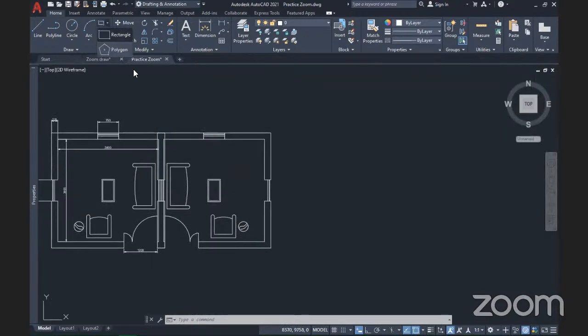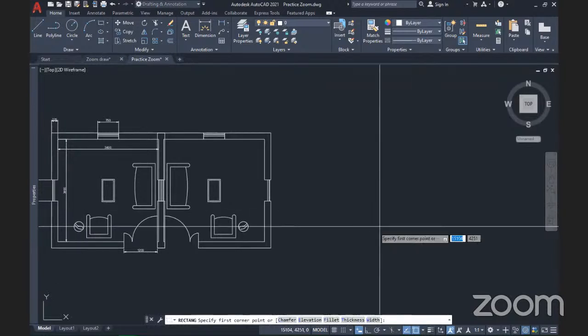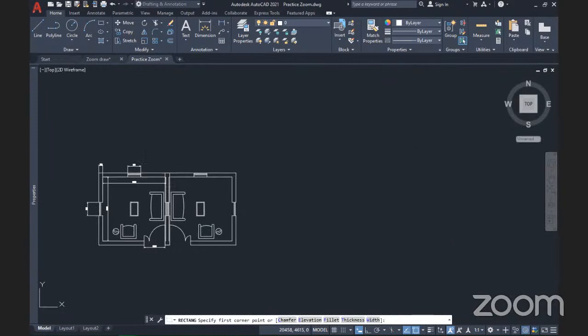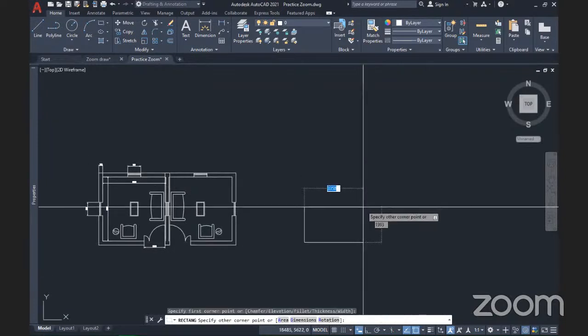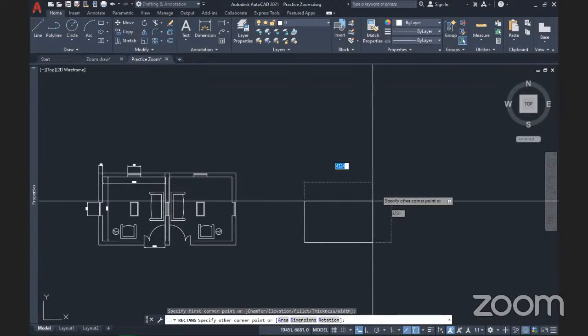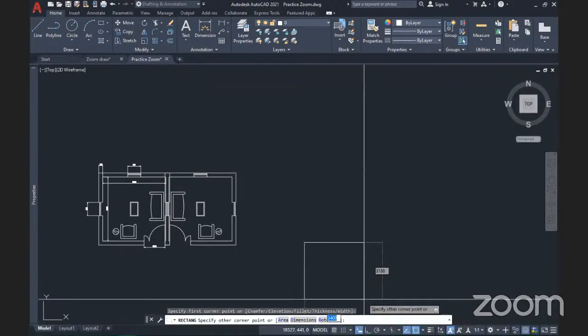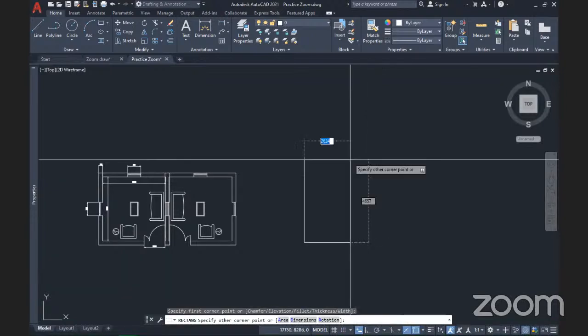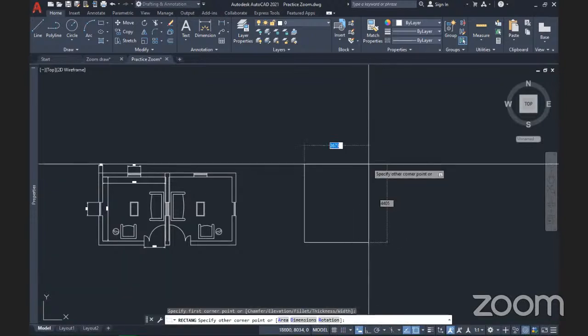rectangle tool to do that. So I pick on any point. It doesn't have to be any special point. I just pick on any point and I draw. And you can see, because my dynamic input is on, you can see two boxes there. One currently saying 3673 and the other one 4405. So that will aid you input the dimensions to the particular object you want to draw.